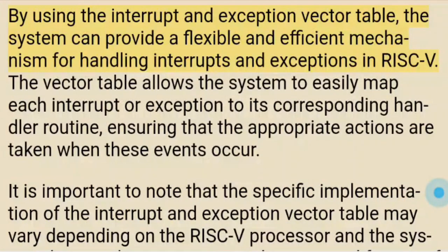By using the interrupt and exception vector table, the system can provide a flexible and efficient mechanism for handling interrupts and exceptions in RISC-V. The vector table allows the system to easily map each interrupt or exception to its corresponding handler routine, ensuring that the appropriate actions are taken when these events occur.